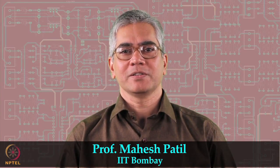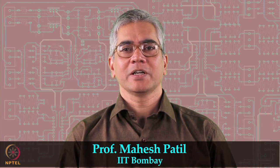In summary, we have completed gain calculation for the common emitter amplifier. Also, for a given input signal, we worked out the complete solution, that is DC plus AC, and compared it with simulation results. We have taken a qualitative look at the variation of the amplifier gain with frequency and pointed out the factors responsible for this behavior. In the next class, we will look at the general representation of an amplifier.